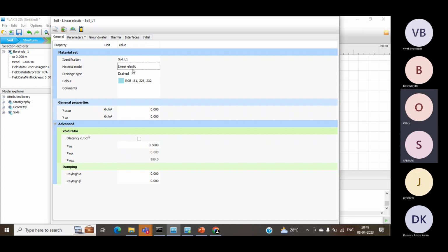Expect this guy, material and water content, right? Sorry, material and water content. Water content here is helpful just to calculate the pore pressures. For a particular soil layer, from which layer you would like to calculate the pore pressures, it will calculate it. That's it. We are not doing any flow analysis here. Later on, we will come to that.